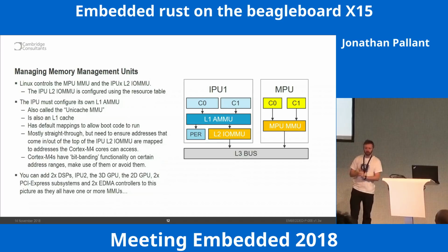They operate a level 1 cache, but there's also a certain amount of address translating. Who here is familiar with bit banding? It's this region of Cortex-M address space where every 32-bit word in my address actually only affects a single bit at a time. It's really useful for doing atomic stuff because I can do a 32-bit write, but only one single bit of memory is flipped, and I can do that in a safe fashion. Super useful feature built into every Cortex-M at a specific address. It's specified by ARM. These addresses are bit banding addresses, and magic happens here.